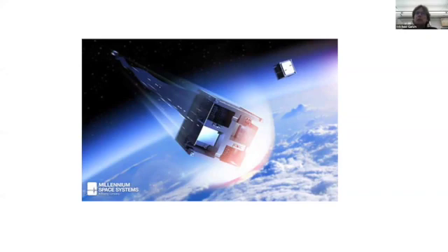Most orbital payloads, you want them to burn up before they fully re-enter the atmosphere and maybe fall down on somebody. So when you're at the end of your satellite's life, a lot of times you're coming back down through Earth's atmosphere and burning up and encountering strong air drag and strong deceleration. And if your satellite hasn't burnt up yet and it's still alive, you can measure this linear deceleration. And from that, you can back out what type of air drag you may be encountering.